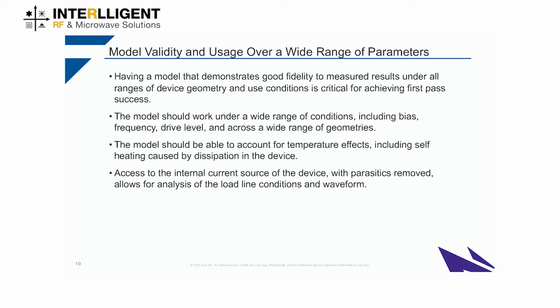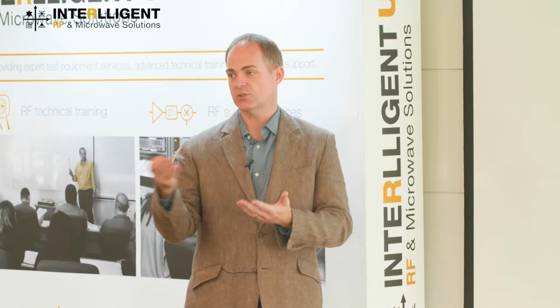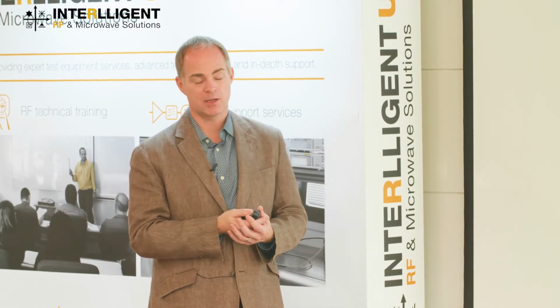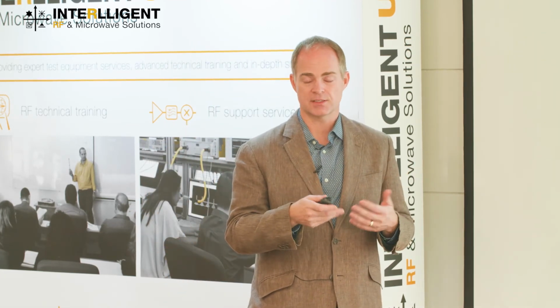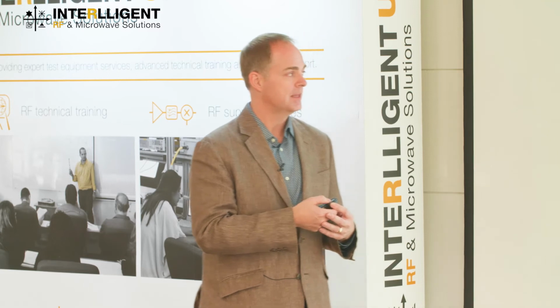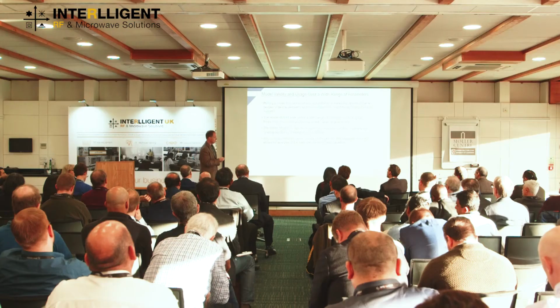And then access to the internal current source of the device is also a key component nowadays in design. This allows you to actually see what the waveform is at the current source intrinsic to the device so that you can do the switch mode design that we were talking about earlier, and also so you can see the dynamic load line, which is very useful for things like distributed designs and understanding how you're actually loading the device.